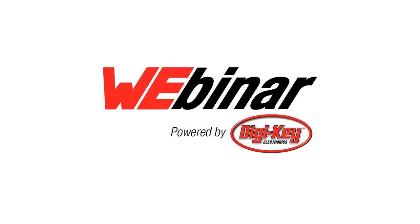Okay, so that was that slide where I had a lot of complicated maths, too many numbers on it. What I used is I know the frequency that it was oscillating at on the PCB. I know the frequency that the crystal would oscillate at in perfect conditions because I took it off and measured it on the network analyzer. And I have the trim value. So that's the value of how much the frequency changes if the capacitive load was 1 picofarad either side.